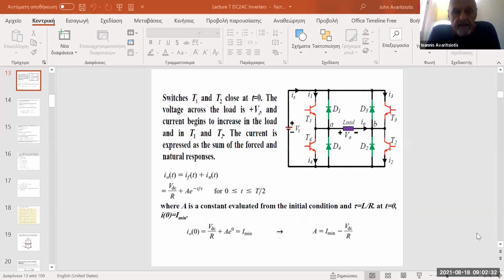order, connected as it is shown on this circuit, in order to decrease power losses by allowing the energy which has been stored in an inductive load, in the case in which your load is highly inductive, to return back to the source, to the DC voltage power source with a voltage Vs, which is connected at the input of this full bridge inverter.